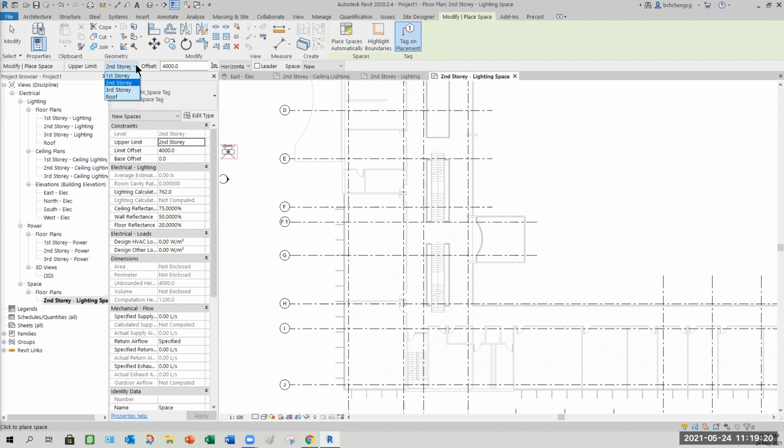If I have a plenum level, that means I will have a level 2 plenum. What I'm trying to show you is that this method can be similar for your first story, which has no ceiling. You tell it, since I don't have a plenum, I'll still select second story, but the offset is only up to 2600. You guys get what I mean?